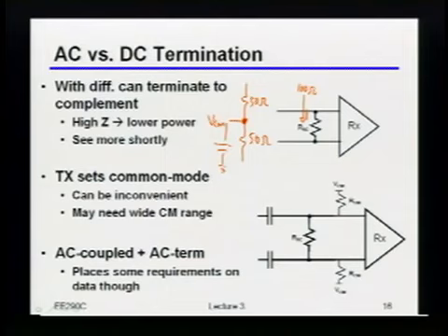Yeah. Now the supply moving around kicks into play. Right, exactly. So now, because my common mode is directly set by the transmitter, if the transmitter is bouncing around relative to me, then that's directly coupling into my common mode. Now, hopefully I have a high common mode rejection in the receiver, but indeed I'm much more coupled than I used to be.